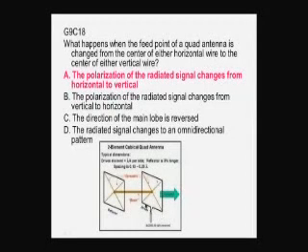For high frequency, it makes no difference whether you have a vertically or a horizontally polarized signal in most cases. But you can change the polarity on the quad antenna by changing where you put the feed point. To do that with a Yagi, you have to turn the whole antenna 90 degrees on its side, the way we normally think of an antenna that size, to make it into a vertically polarized antenna.